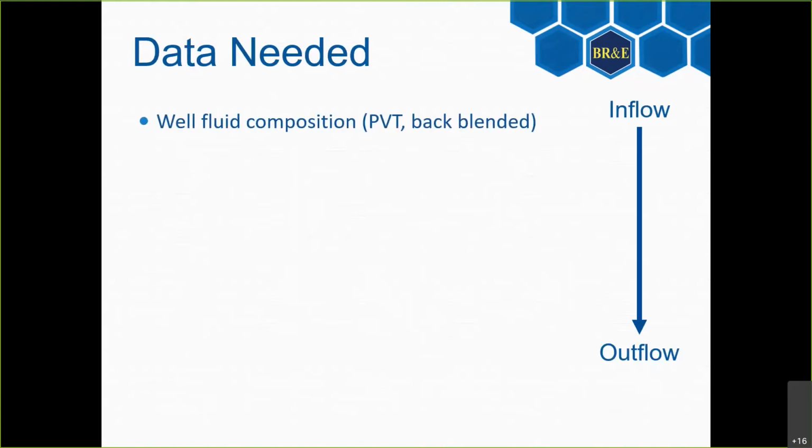The composition of the well fluid plays a big role in all of the physical properties that govern the inflow and outflow performance. So normally you get that one of two ways. If you have a PVT on hand, then we can use your PVT analysis to find the composition. PVT analyses have composition in them, so that's a test that you can run that will give you information about your well stream fluid. Or if the only samples that you have are further downstream, let's say you have a pressurized liquid sample or maybe your oil sample of what you're selling, and you have your sales gas sample, we can do a procedure called back blending to get that well fluid composition.